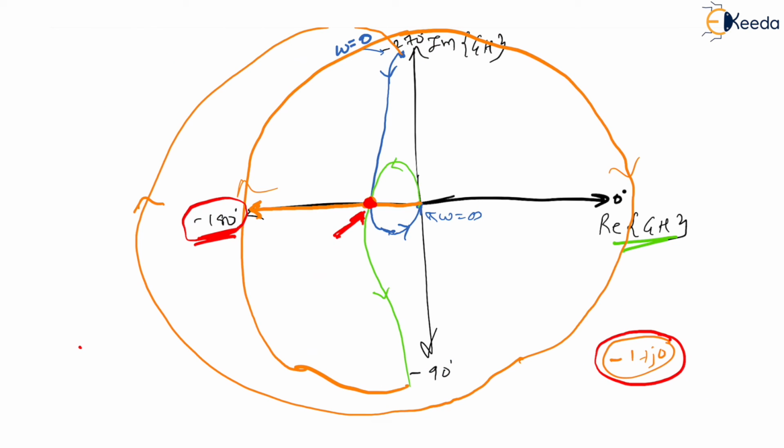So this particular point is nothing but -0.2, which means -1 has to be somewhere here. Is that correct? Why? Because these are infinite radius circles. You cannot say, sir, please put -1 here. No, it doesn't happen that way. It cannot happen, because these are infinite radius circles, right?